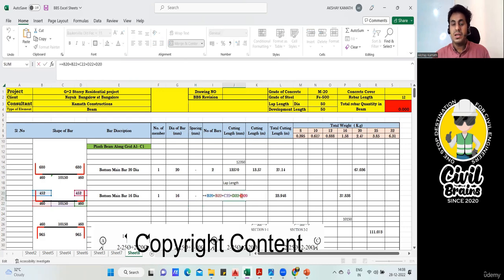Now coming to the total cutting length. Cutting length total will be 472 plus 460 plus 10,150 plus 460 plus 452. Got it? Now, one question: should I add a lap length here? No, not required. Why? Because this total cutting length is 11,974, which is less than 12 meters. So one 12 meter bar is sufficient for me.